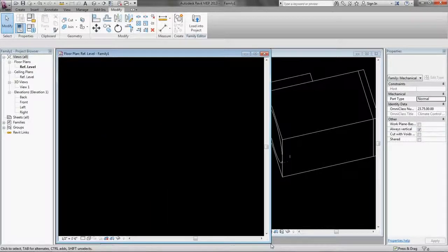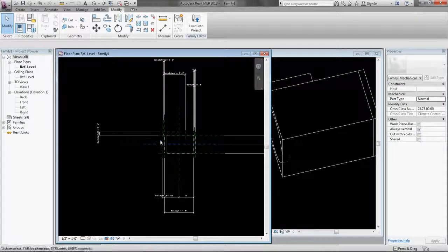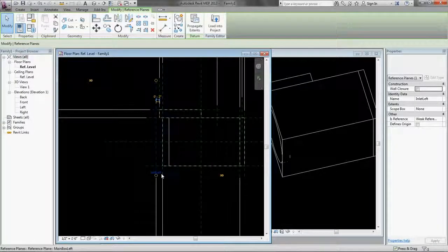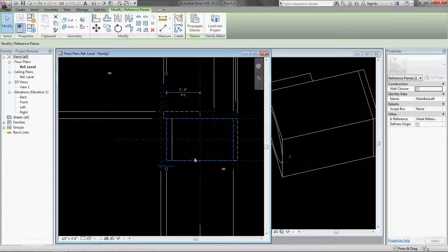If you've done much 3D modeling before, you might be familiar with the concept of normals. Faces and planes in 3D geometry have normals, which is the direction that's orthogonal to the plane. Orthogonal is another word for perpendicular. So the normal for this plane, the one that I sketched on, is to the right. And that's why our extrusion is popping into the box instead of out of the box.